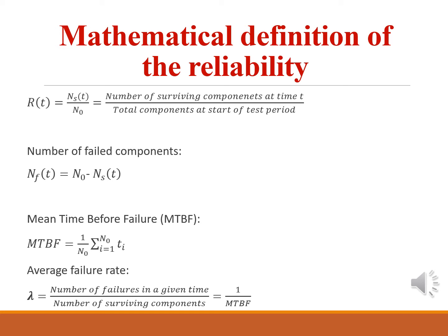The testing is carried out under rigorous conditions, representing the worst operating conditions likely to be encountered in free space, and may be designed to accelerate failure in order to shorten the testing duration needed to determine reliability. Units that are exposed to the vacuum of space are tested in a vacuum chamber, and components subjected to sunlight are tested under equivalent radiant heat conditions.